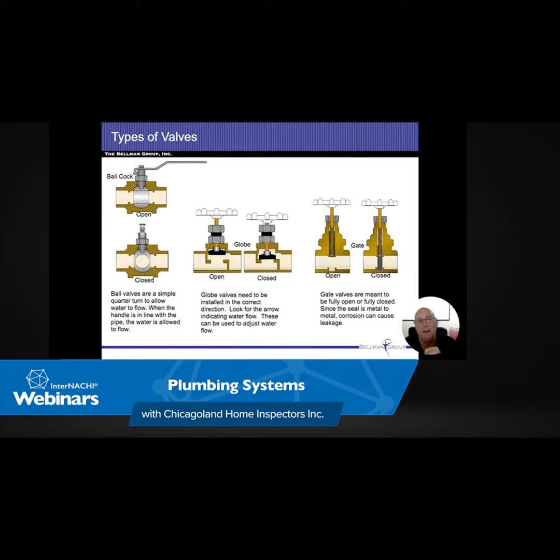Now these dip tubes, that blue pipe that's going down to the bottom, they're fragile, all right? And they do deteriorate, they do break. And if they do break off and it's gone and it's sitting inside the tank, we're not going to see that and we're not going to know it. What's going to happen is that now cold water is going to be introduced into the tank at the top.